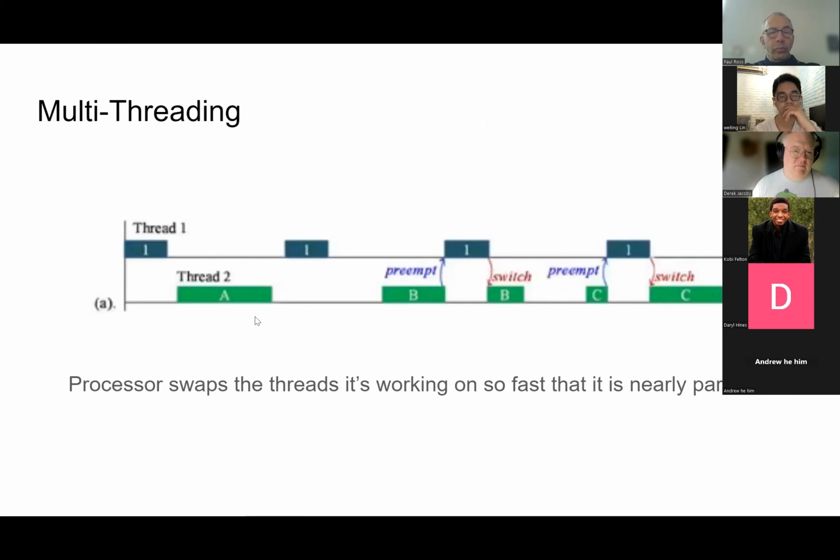So that's the abstract. What it often means in practice for a microcontroller is that you have one processor which can do one thing at a time. Most laptops and phones now have multiple processors, and there's some deep magic that handles a lot of that. But if you have a really cheap, simple microcontroller, you basically have a meta process that is deciding what work to work on if you need to do two things at once. An example for me is, I want to measure a temperature, and then I also want to send that temperature value over the network so that someone knows what temperature it is. And that someone could be anything.